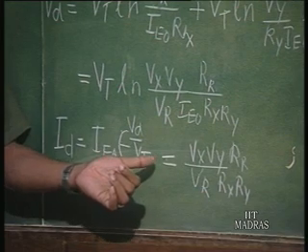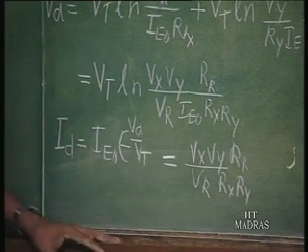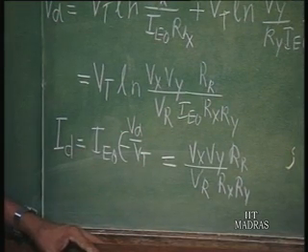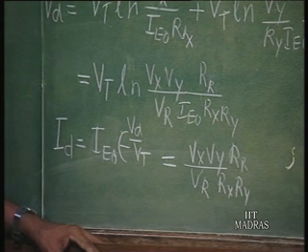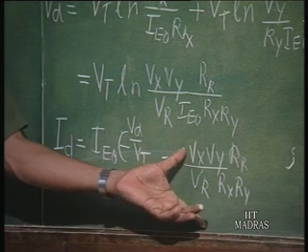So, I illustrated this as a place where it is not necessary to use compensated amplifiers, because when you take log and antilog, the effect of both V t and I e naught get cancelled. So, this current is got.